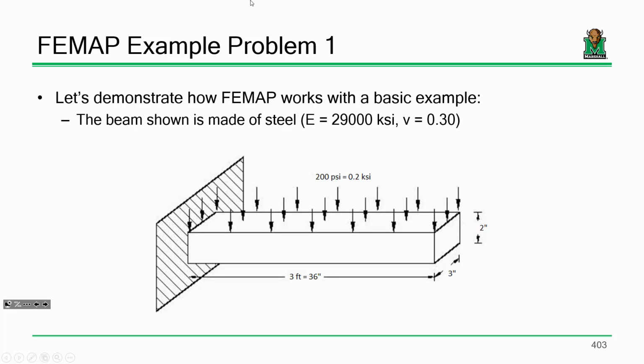So let me ask you this. When we get our results from this problem and we look at deflections, what are our deflections going to be in? Inches, right? What's our stress going to be in? What is stress measured in? KSI. Okay, you see what I mean? That's the stuff you've got to be consistent with. Same units going in equals the same units going out. Now we could easily put in 29 million and put a load of 200, and then our stresses would be in PSI. It doesn't matter as long as you're consistent.